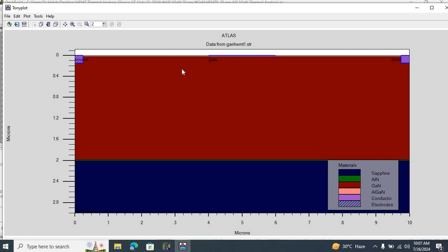So to summarize, we have undoped gallium nitride and aluminum gallium nitride layers. These could be lightly doped as well. We might have a lightly doped buffer layer, where the doping level is really low to reduce the leakage currents. And then we have heavily doped drain and source regions to form the contacts. Now this doping strategy ensures a high electron mobility two-dimensional electron gas at the gallium nitride aluminum gallium nitride interface, providing the gallium nitride HEMT with its superior high power and high frequency performance.